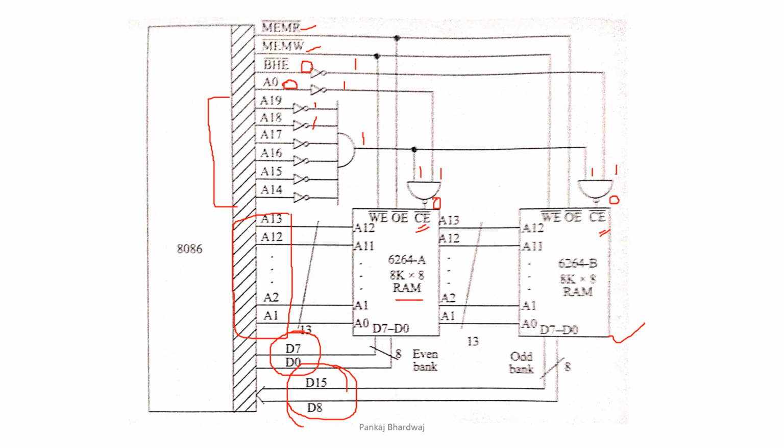In this similar fashion, we can have any address combination. If we choose A19 to be 1 and the rest are 0, then for every single 0 we need to place an inverter, and for every single 1 we need to replace the inverter by a simple line. That means no inverter is connected. So if A19 is 1 and all others are 0, all other lines are connected to inverters but not A19. So the address range can be accordingly modified.